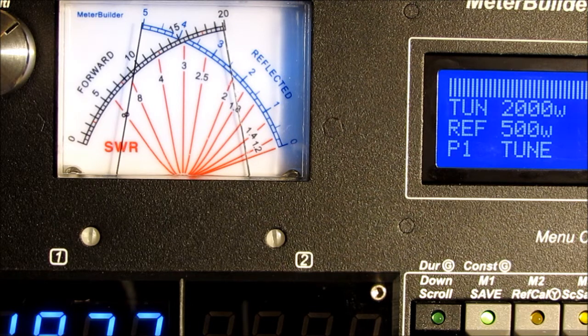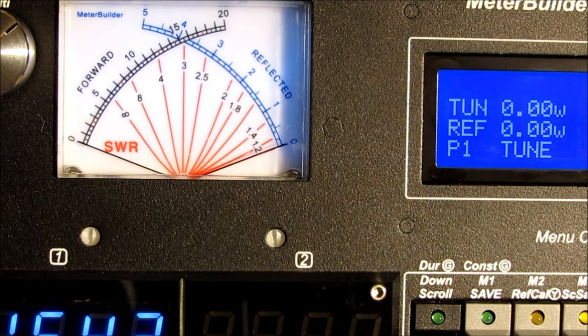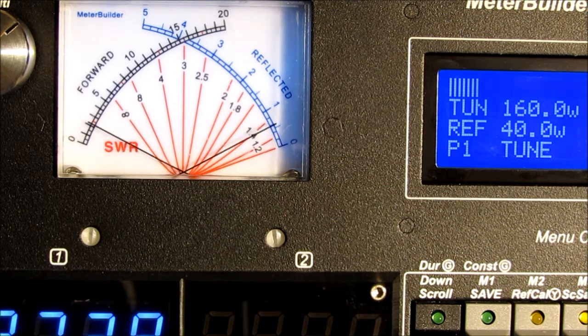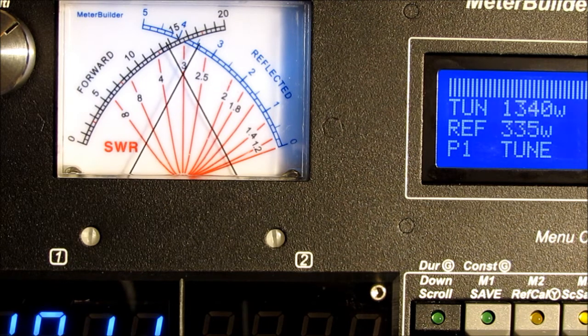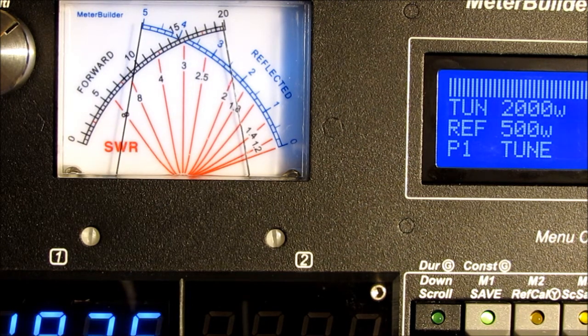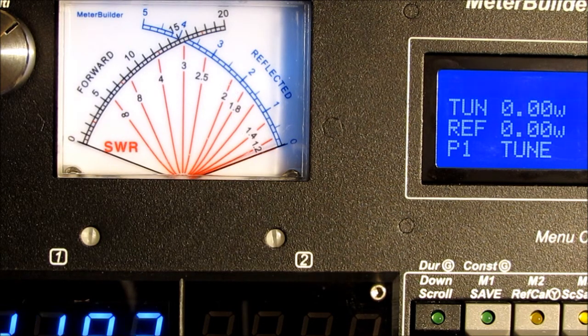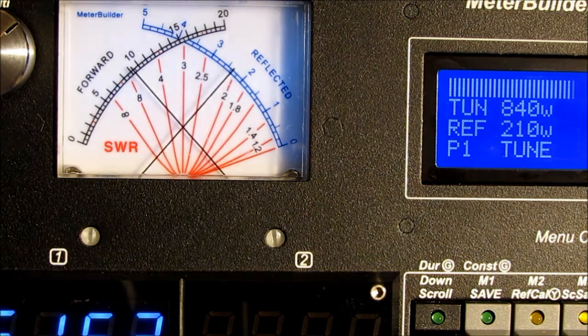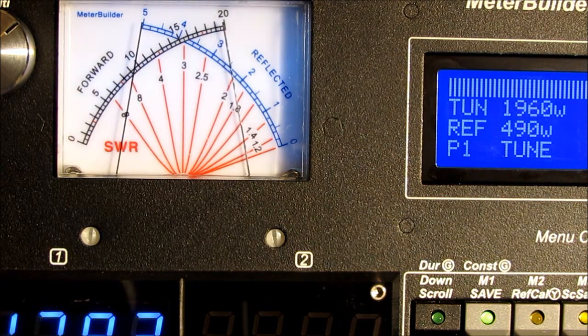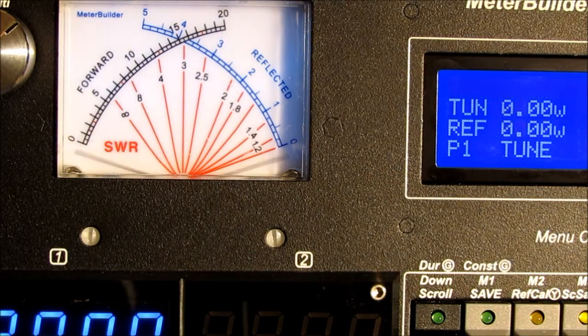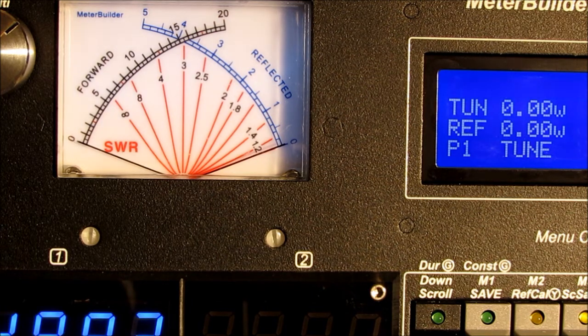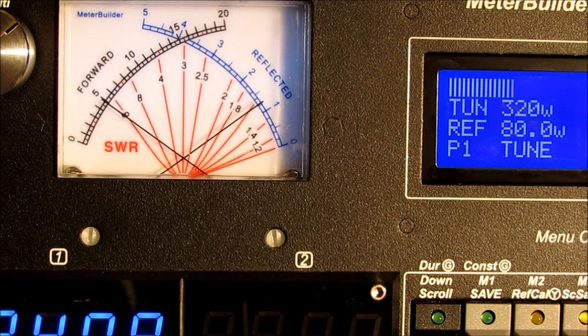Right now, I want to point out that the MB-1 is working in a simulated mode. We're not running real power through it. The inboard simulator is generating a simulated full-scale value of 2,000 watts and a constant SWR of 3, and it is in what we call the simulator sweep mode, generating a sawtooth wave, which is useful for checking the calibration of the panel meter after you've calibrated it. In this particular case, you'd expect to see the forward and reflected needles track the SWR equal 3 curve all the way up. Indulge me for a minute before I explain the menu structure.